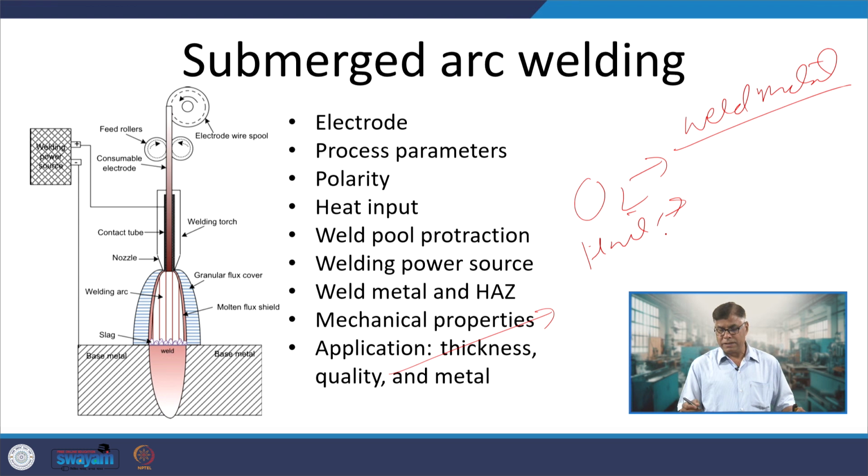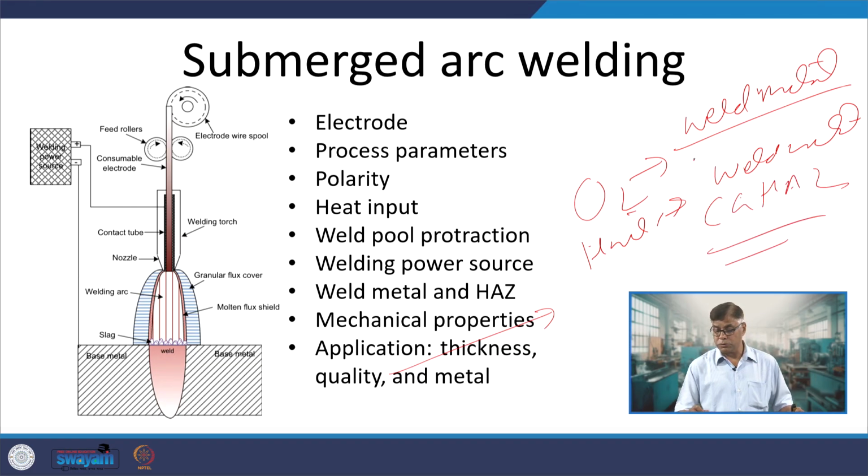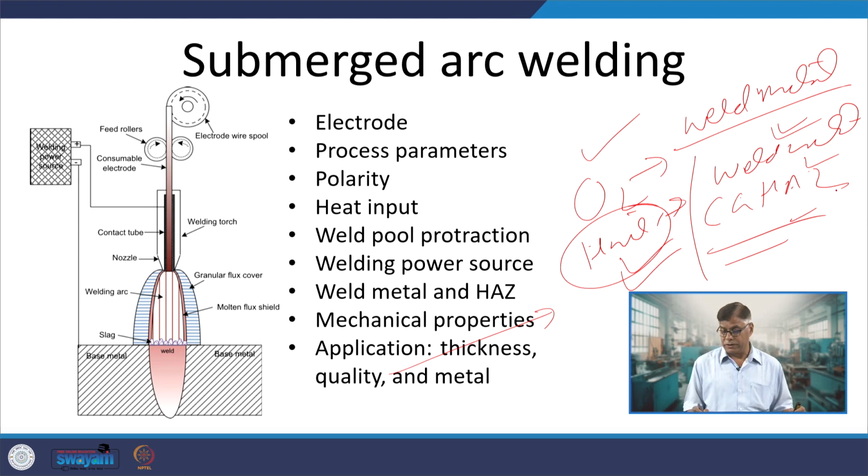So, the weld metal characteristics are not good due to the coarse grain structure, and also the heat affected zone properties, like formation of the coarse grain HAZ. So, these lead to the reduction in properties. So, impurity in the form of oxygen and high net heat input lead SAW to reduced quality of the joints, due to the reduced mechanical performance of the weld metal and the heat affected zone.